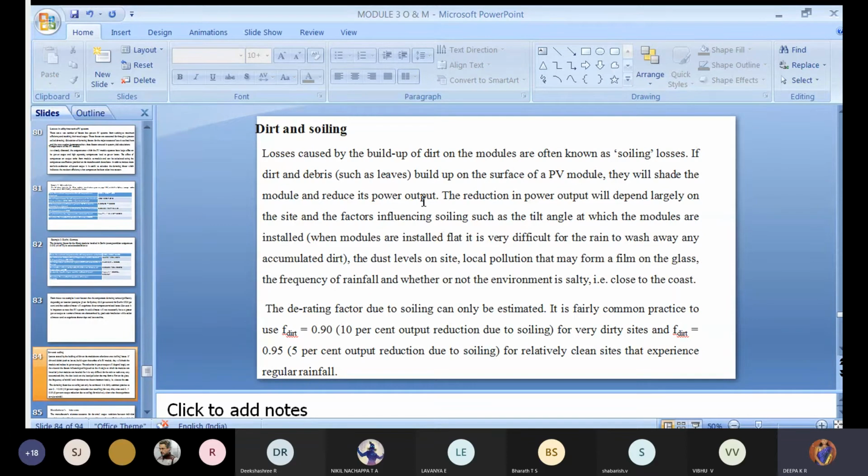So you can reduce those power losses by making a proper tilt angle or a proper orientation, because one of the natural gifts is rain. If it happens, it is going to clean and wash it. If it is slant, definitely it will wash away the dust also, and wash away the leaves also. But if it is not slant, if it is completely horizontal, like a sleeping line, what happens? If rain comes, again it will create more accumulation at one particular cell where the cell cannot operate at all. So that problem you will face.